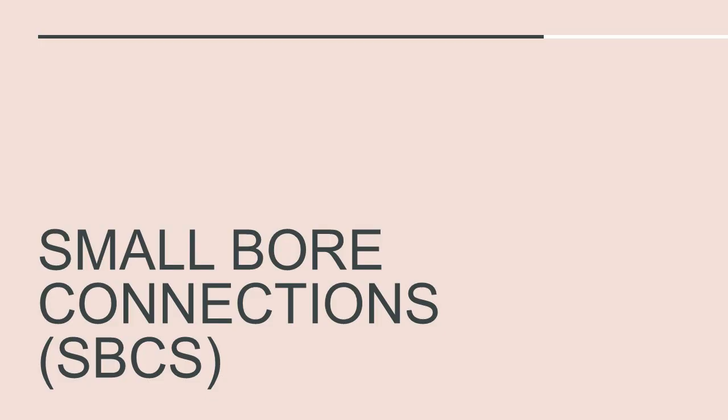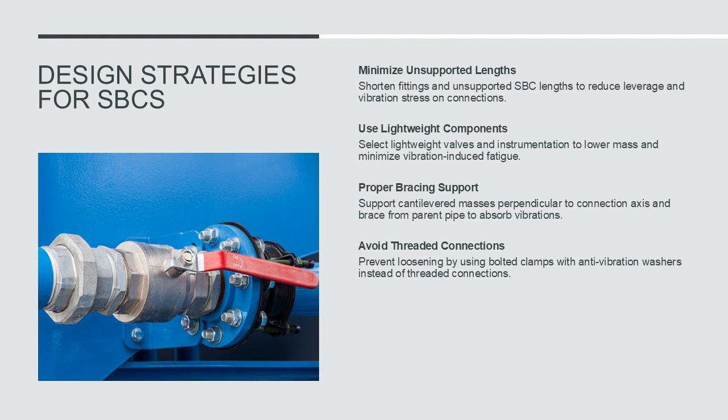Design strategies for small bore connections. Small bore connections, SBCs, are particularly susceptible to vibration-induced fatigue due to their relatively small size and cantilevered configurations. To mitigate these risks, fittings and overall unsupported length should be kept as short as possible, reducing leverage and stress on the connection. The mass of valves and instrumentation attached to SBCs should be minimized, ideally by using lightweight components such as double block and bleed valves or monoflange valves.